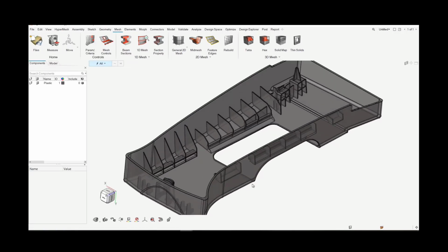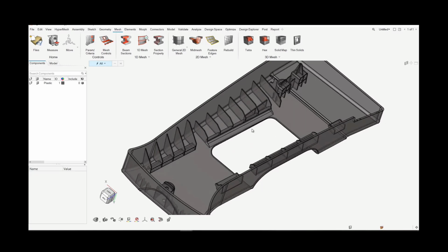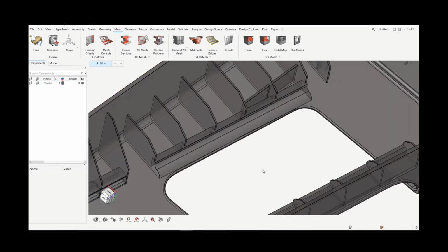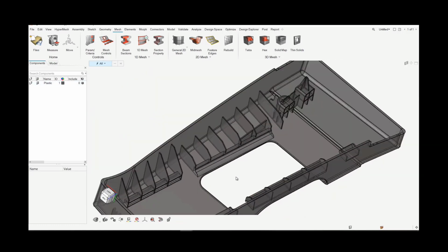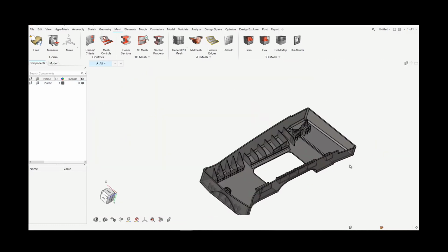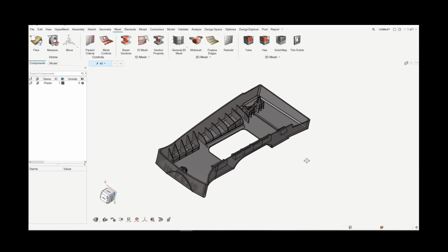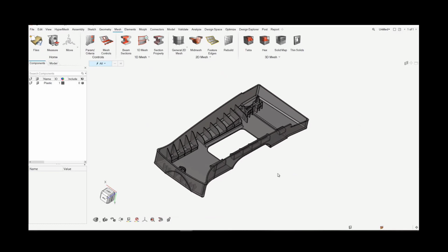And this is some kind of injection molded plastic part, pretty complex. I mean, if we were to go in here and mid-surface it, you'd get a lot of disconnected surfaces that needed to be cleaned up through a decent amount of topology repair. One possible option here is just to bypass the mid-surfacing part of this altogether and use this direct mid-mesh.